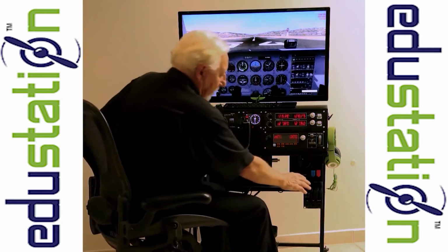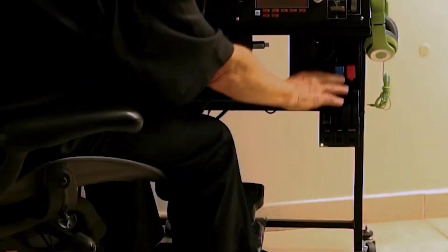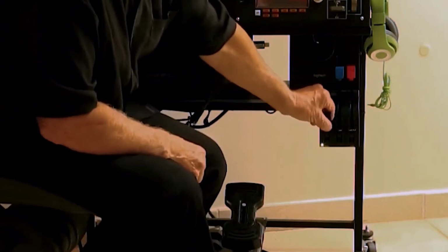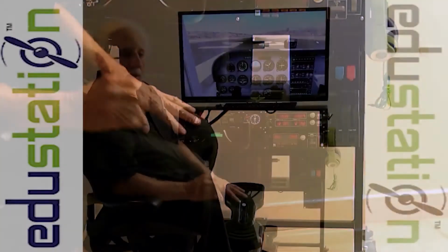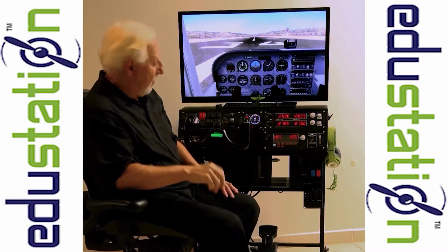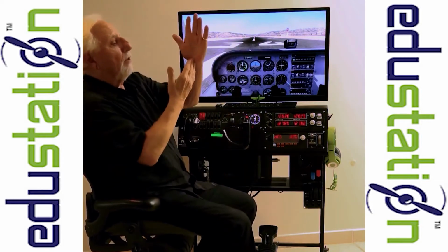And what we're going to look at next is the throttle quadrant to the right. There are 3 vertical levers on the throttle quadrant. The black lever is our throttle or our gas pedal. So when you raise it, you'll go faster, and lower it, you'll go slower. The middle slider is for propeller pitch.